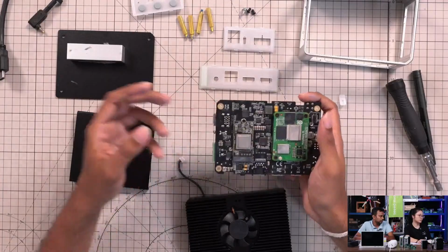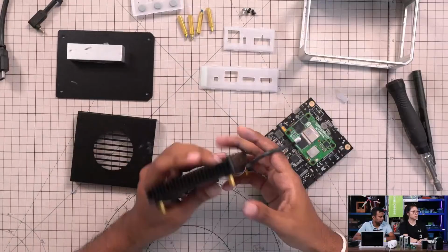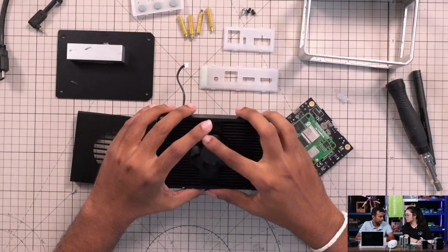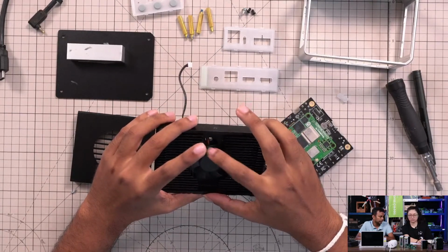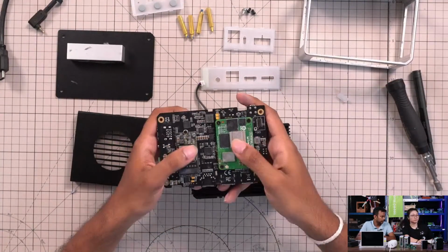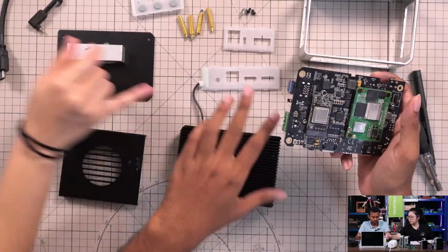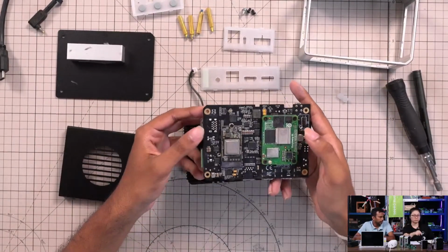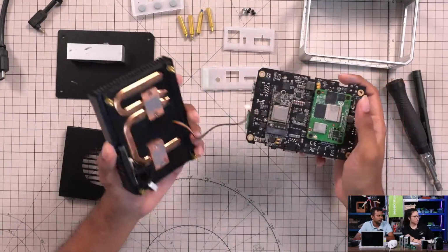So this is the radiator design, and we have an active cooling fan. You can see there are no pins in the low airflow area. The heat-generating components are placed on the left and right sides of the PCB, matching the pinned area, so the pin area with high airflow improves heat dissipation efficiency.